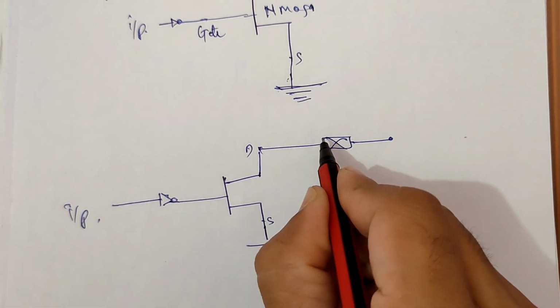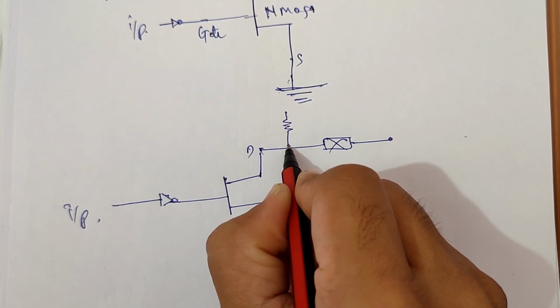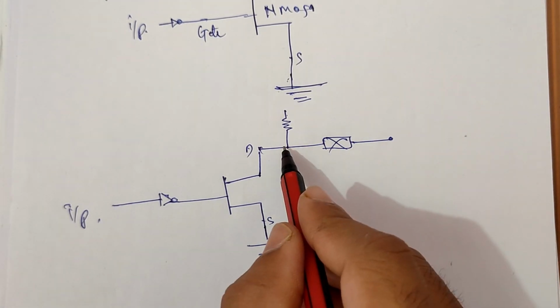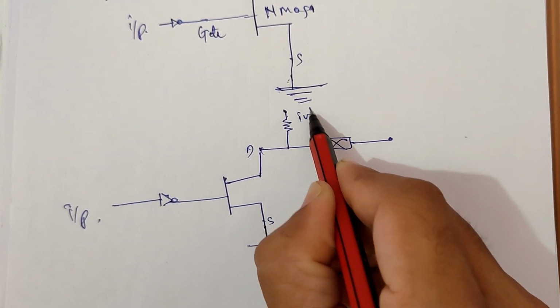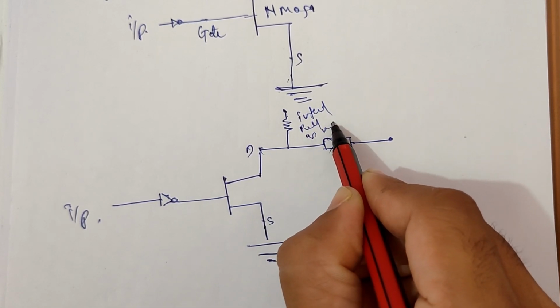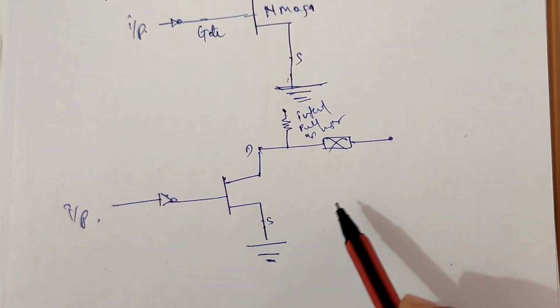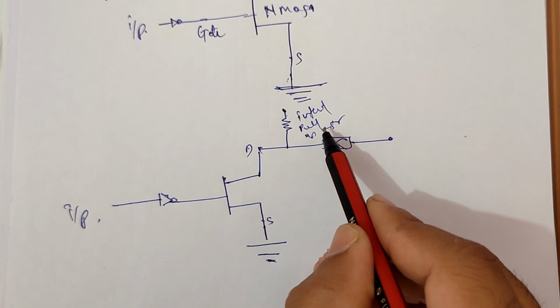There are two types of pull-up resistor. When I connect the pull-up resistor before the pin, inside the microcontroller, that is, the pull-up is available inside, then we call it an internal pull-up resistor. Nowadays the microcontrollers we are using come with this feature, the inbuilt internal pull-up resistor.